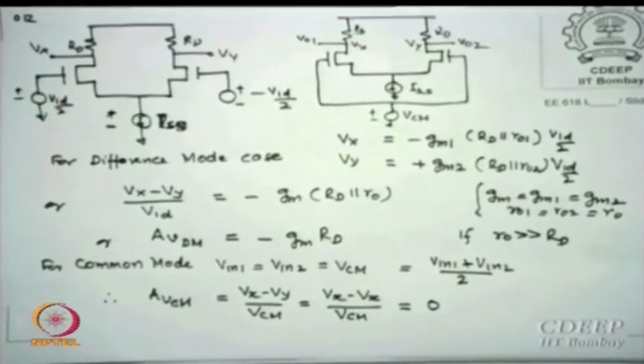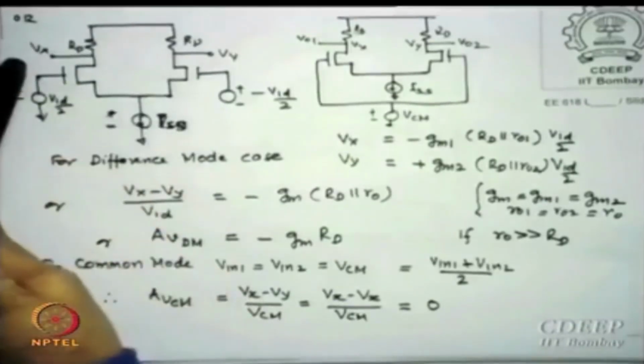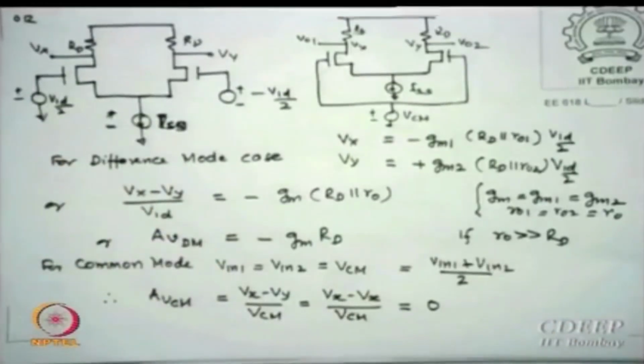So what is the diffamp property? It will only amplify differential signals, and output will go to zero difference if they are common modes. Please remember, individually you can still get outputs in single-stage form, but the difference of them is 0.